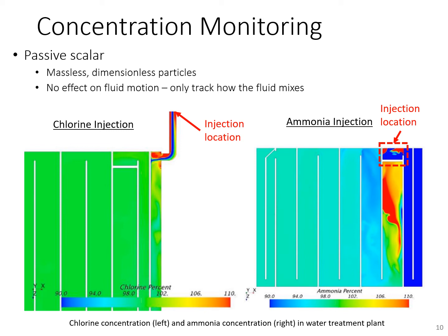These simulations showed that, based on the turbulence induced by both the sudden expansion and momentum change of the fluid in the inlet pipe as it reaches the clear well, the chlorine supply reached close to its final outlet concentration even before it made its first turn in the clear well path.